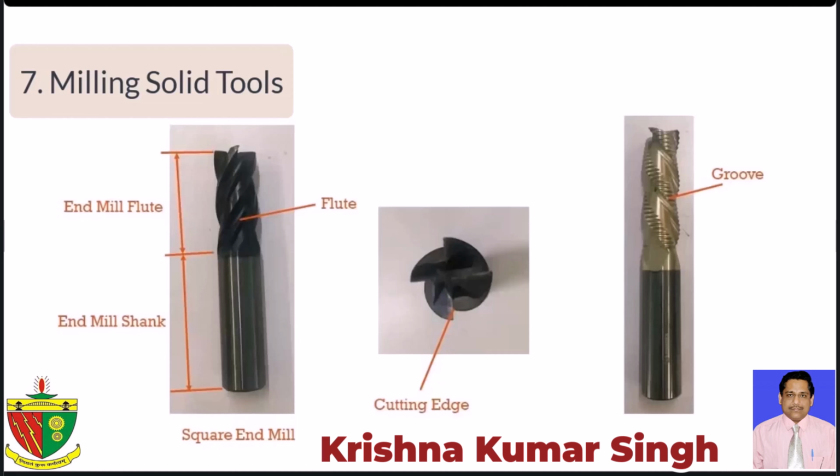However, when there are many cutting edges, there is less room for chips, and the cutting forces are usually higher. Therefore, for roughing operations, it is better to use end mills with 2, 3, or 4 cutting edges, especially when there are issues with chip evacuation. For example, when making a slot or milling materials like aluminum, which produce longer chips, you should use 2 or 3 flute end mills. On the other hand, when milling abrasive materials like hardened steel, you should use end mills with more flutes, such as 6 or 8, so the wear is distributed among the cutting edges.